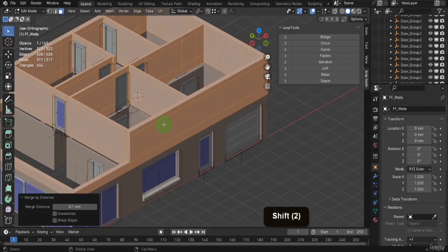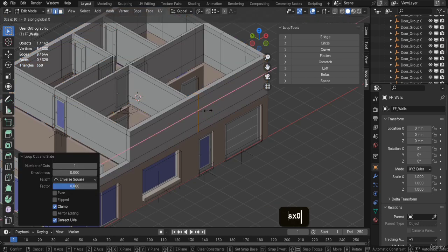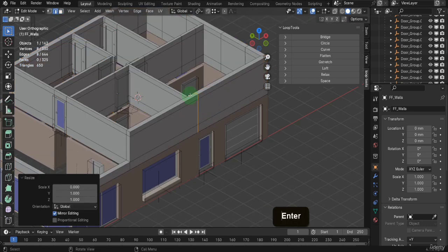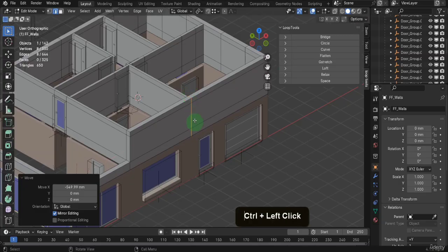There are a couple of ways to remove the faces for the windows, then fill around. We saw that with the balcony when we filled back in around the wall. We need to add 4 edge loops first. These will be the window boundaries. Press Ctrl plus R and add an edge loop here. Press S, X, input 0 and enter. Now snap this along the X and to this internal wall here.